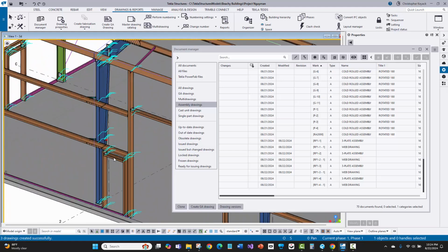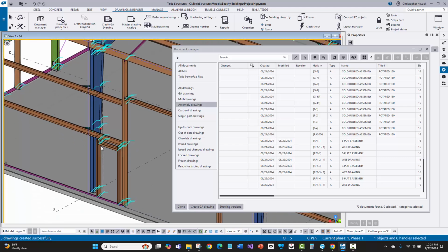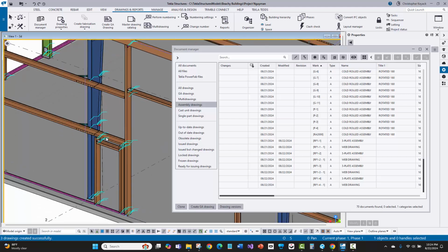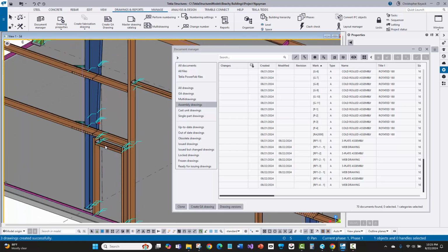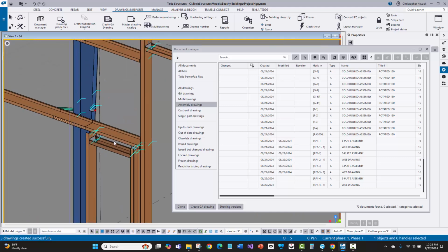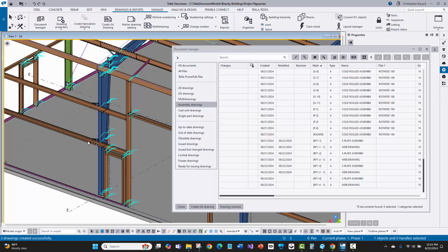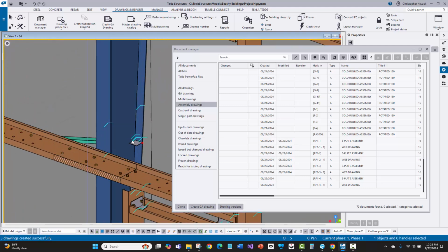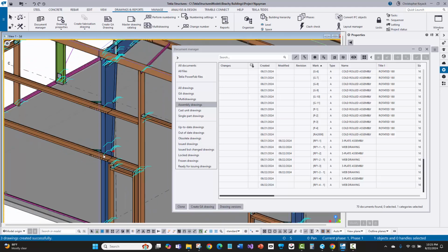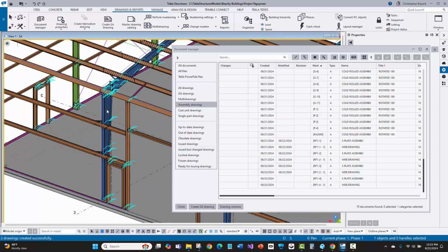However, I had a situation here with this walk-through door opening and the Girt elevations that were done on the building input; this wasn't originally working. And so just on this Girt line, we actually moved this up in Tekla rather than doing it in MBS, and checked that with the engineer to see if that was okay. So this particular Girt line is a little bit higher, which means that the flange brace clips are moved up as well as the Girt clips. So what did that do? That made this assembly different than the other ones.